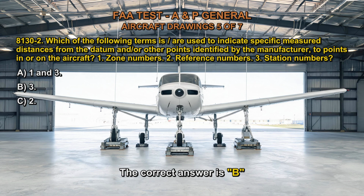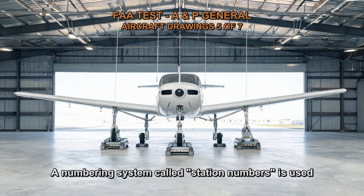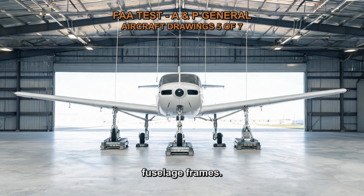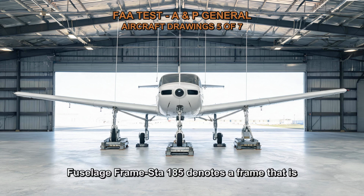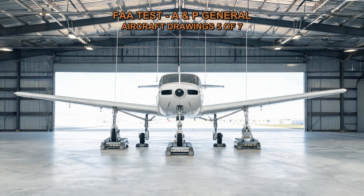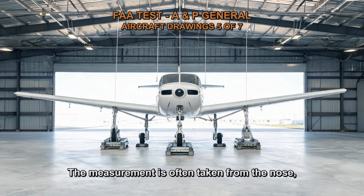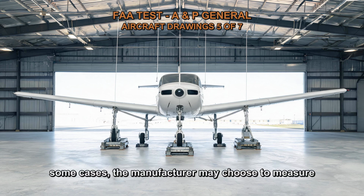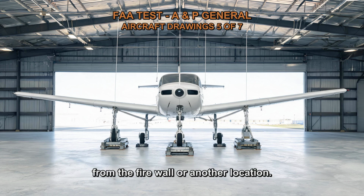The correct answer is B. A numbering system called station numbers is used on substantial aircraft assemblies to identify stations like fuselage frames. Fuselage frame STA-185 denotes a frame that is 185 inches away from the aircraft's datum. The measurement is often taken from the nose, also known as the zero station, although in some cases, the manufacturer may choose to measure from the firewall or another location.